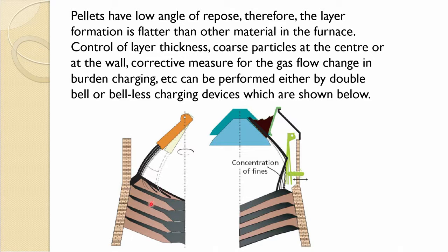And now you are already aware of how the burden distribution can control the gas flow, and not only the gas flow, this gas flow in turn controls the heat transfer and mass transfer, which is very important. So, these are the things which are very important in terms of distribution of the burden charge.